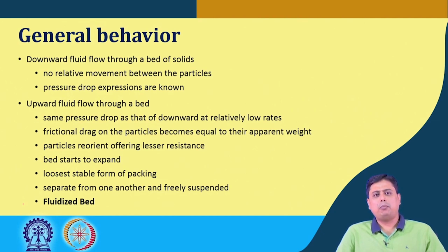Now in case of upward fluid flow through this exact same bed, if those solid particles are unrestrained on the top surface, like the problem we solved in the flow through packed bed section, when the particles are just stacked on a porous support through which, let us say, gas or liquid is flowing upward, then the pressure drop expression is the same as for the downward fluid flow, but at relatively low flow rate, that is valid.